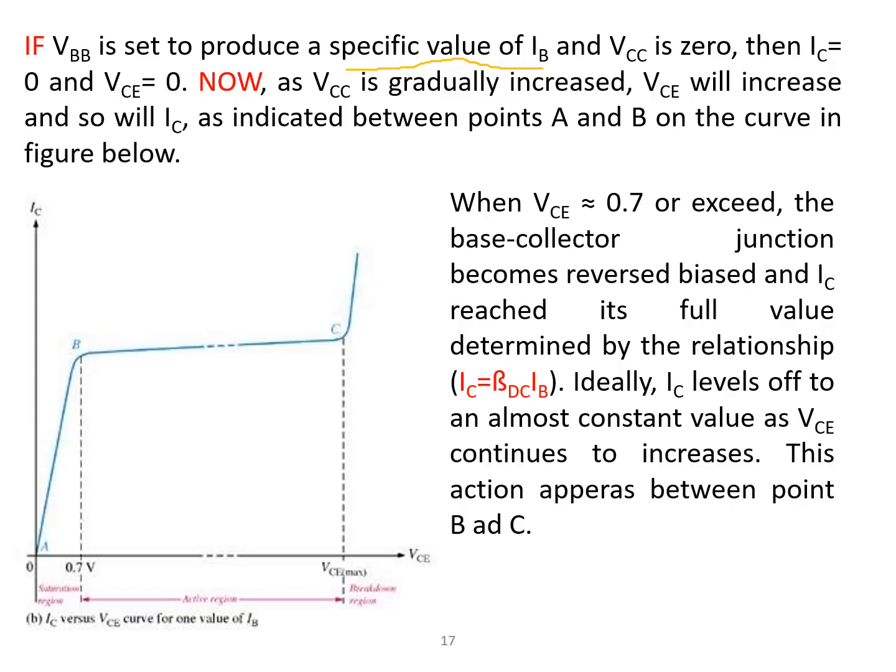Now, as VCC is gradually increased, VCE will increase and so will IC, as indicated between point A and point B. As VCE is increased, IC also increases.